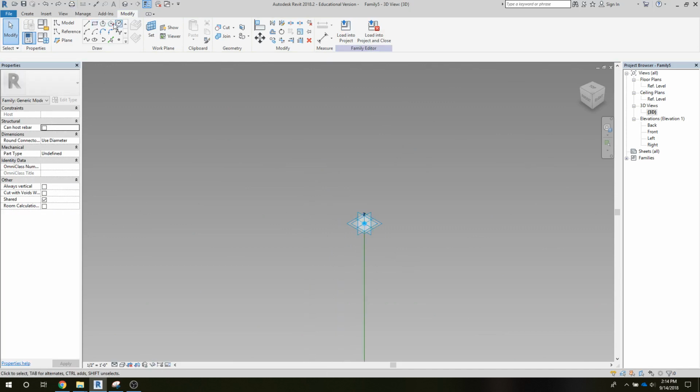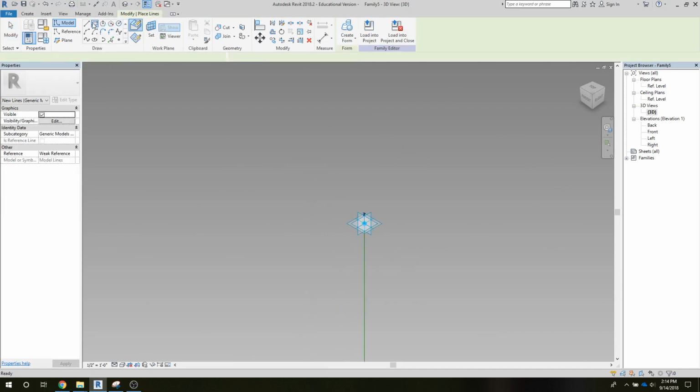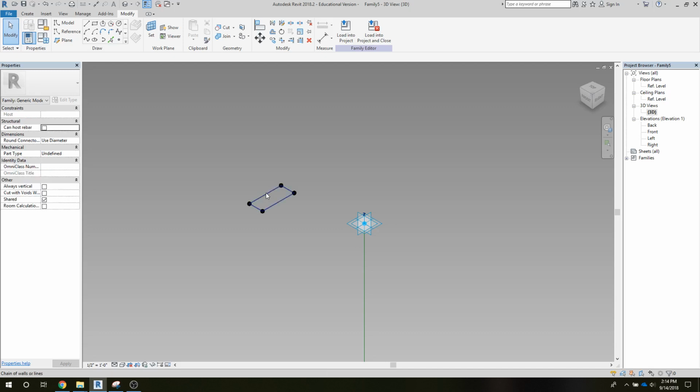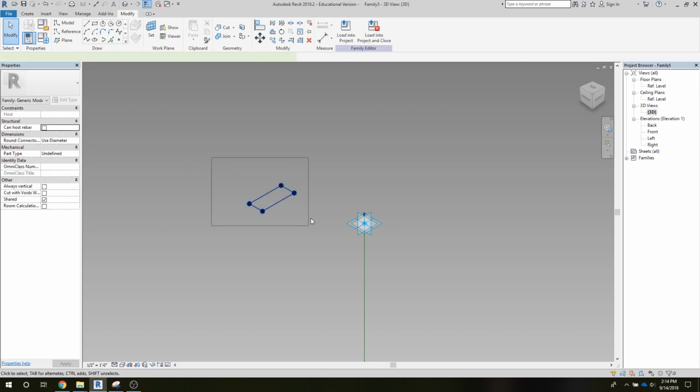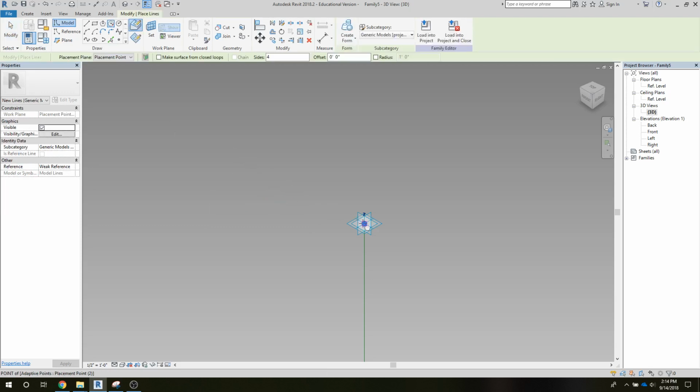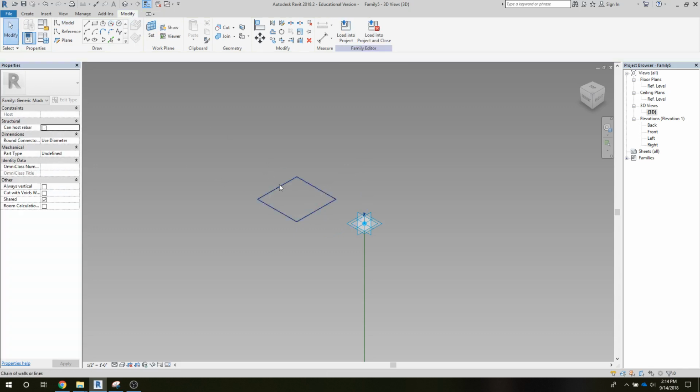So let's go ahead now, and I'm going to zoom in. The rectangle always gives me more trouble. When I try to draw with it, I find that we get no way of pulling dimensions off of it quickly. I'm not exactly sure how that's supposed to function. So I'm not going to use that tool. I'm going to use the polygon tool, and I'm just going to make a polygon anywhere. And we really want to be, let's say 12 inches deep with our column. And we're going to resize that.